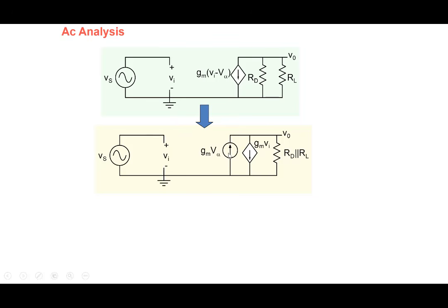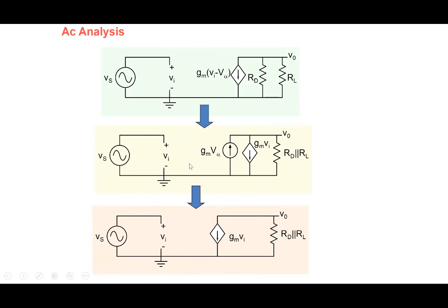Now note that our interest is basically in the sinusoidal part here: the sinusoidal current, the sinusoidal output voltage. We are doing AC analysis. Now, V alpha is a constant and gm is a constant. So this is a DC current. And so when your interest is in the sinusoidal part, you can ignore this particular part here. You can forget about it and just keep these parts here.